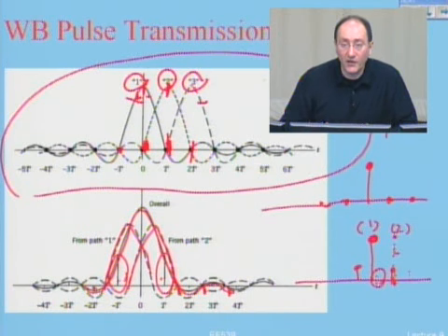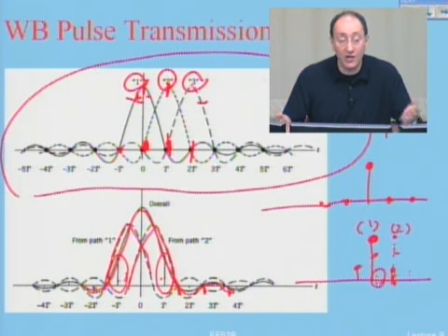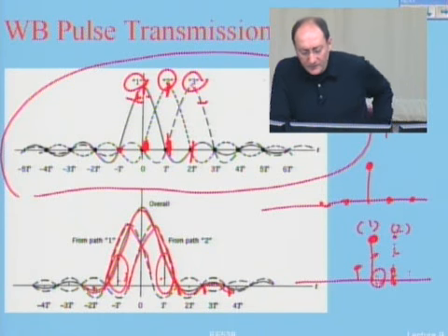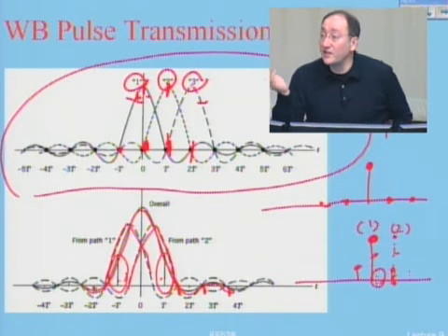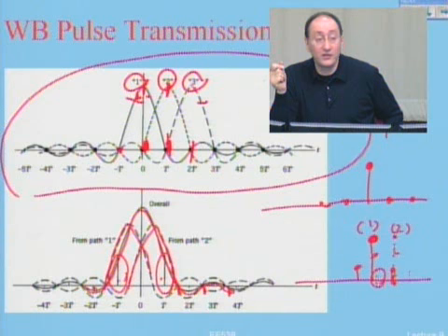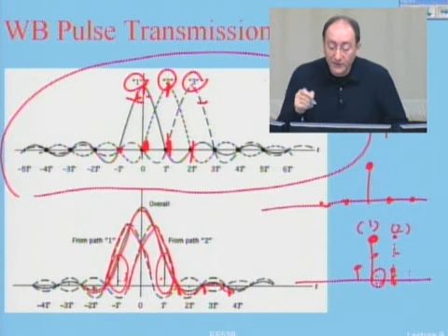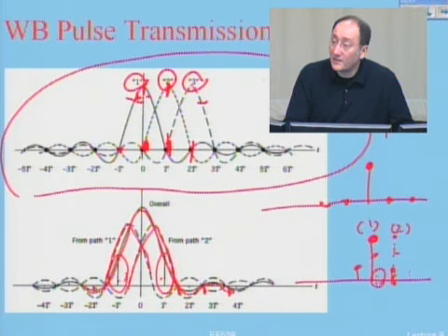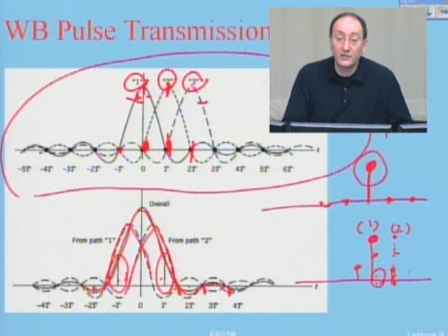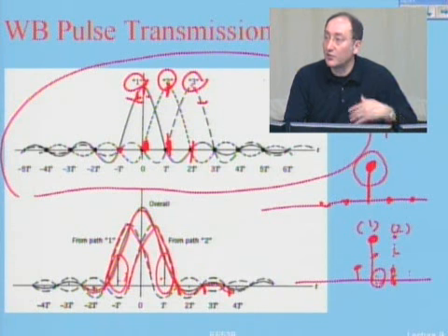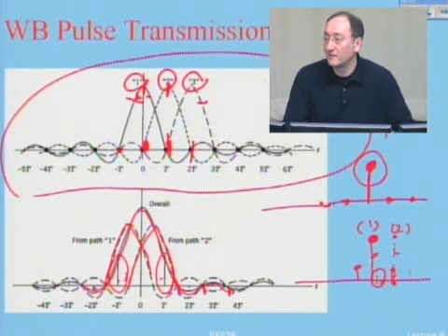Now, if I increase the power, both the signal and the side lobes increase, and I cannot solve the problem. Okay? So it's not a bad idea to think in a discrete manner. I like you actually to think in a discrete manner. I'm talking about a fading channel. If I have a narrowband signal, my impulse response is only one pulse, which is changing its amplitude according to the fading. It goes up and down.